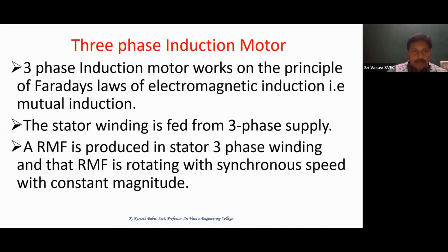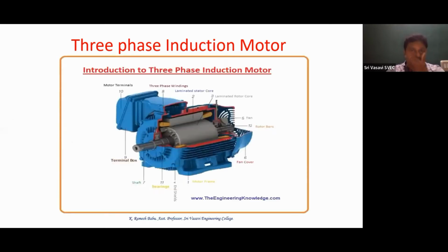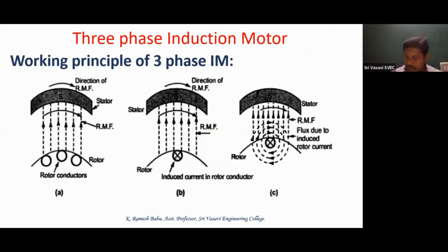Okay. So when the three-phase supply is given to the stator three-phase winding, a rotating magnetic field is produced in the stator three-phase winding, and that rotating magnetic field is rotating with constant magnitude and with synchronous speed. Coming to the working of three-phase induction motor.